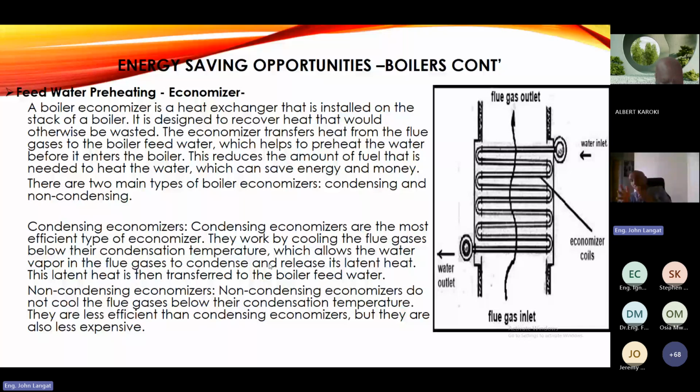But you need special equipment here. Once you install this, then you need a special pump. You are not going to use the ordinary feed pump. That one will just blow out if you use that. And that's why you need to keep an eye on this temperature if you are not using that.